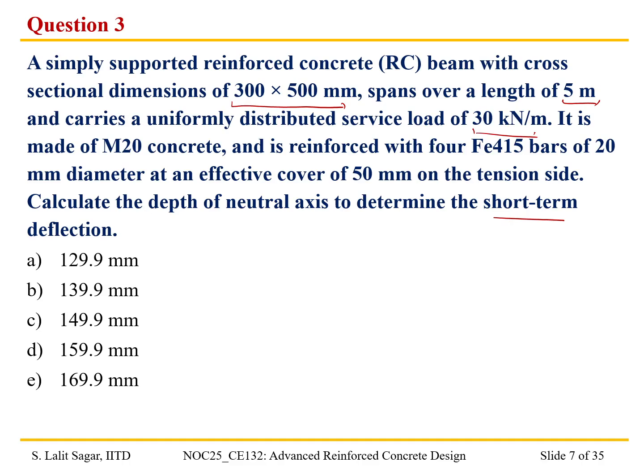So we are going to solve this problem in order to determine the short-term deflection of the reinforced concrete beam. First we are going to start with sketching the cross section, and then we'll try to locate the depth of the neutral axis, and let us not forget that we need to solve this problem as per the working stress method.